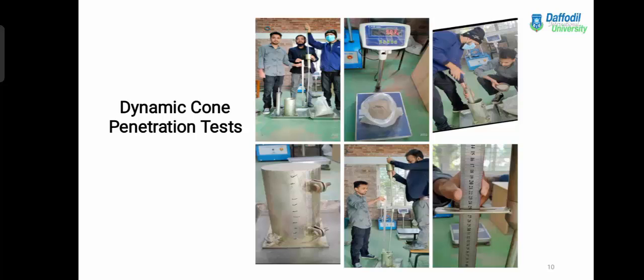A 147.32 mm diameter and 304.8 mm high mold was used for specimen preparation. The specimens were compacted in 6 equal layers, with an equal compactive effort using a standard Proctor hammer, and the targeted density was achieved by trial and error.